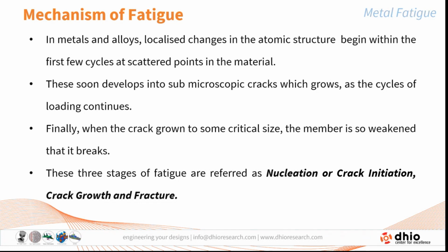Here, the mechanism of fatigue is classified under 3 main headings. One is in the metals and alloys, we see that there are localized changes in the atomic structures, which begin within the very first few cycles at a scattered point in the material. This is the peculiar behavior, whereas in static loading, it is not going to change the localized atomic structures. In static loading, it is going to be distributed among the atoms, and then all the atoms try to resist the loading.